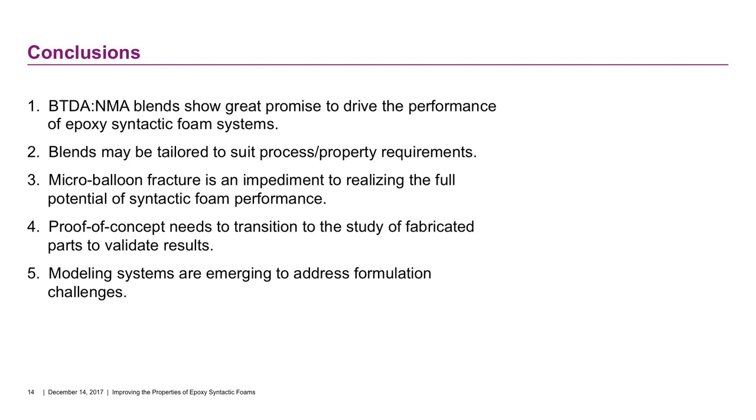The other thing we've uncovered, which certainly isn't new, but from our standpoint, we just have found that the microballoon fracture which we have experienced can really be an impediment to realizing the full potential of these systems. So if you want to drive compressive strength and now you've got a certain percentage of fractured microballoons that you have to deal with, you're not going to get to where you want to go.